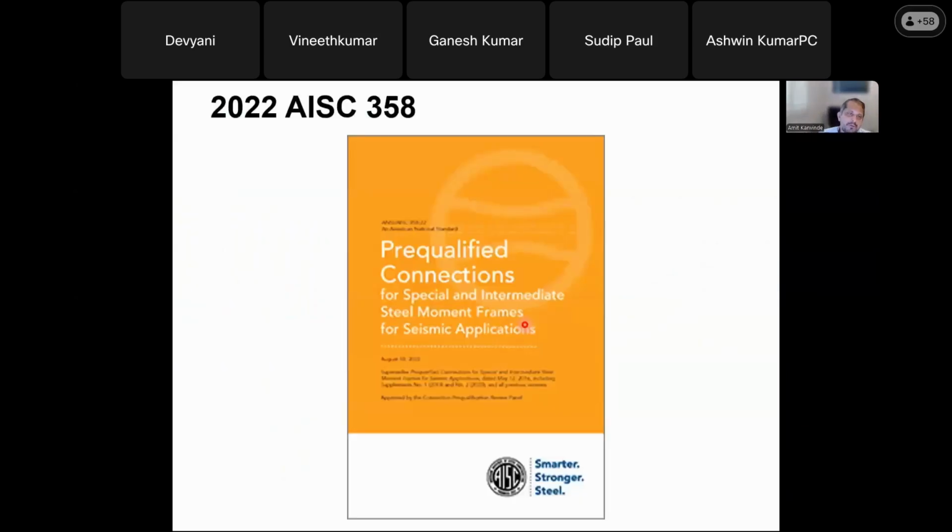I want to point you to another reference here, which is AISC 358. This actually gives us recipes, or very clear procedures, for designing different types of connections that meet the ductility requirements for special moment frame application. This is something that, again, is free for download. You could just download that, and if you look at this, you'll be able to see how to make